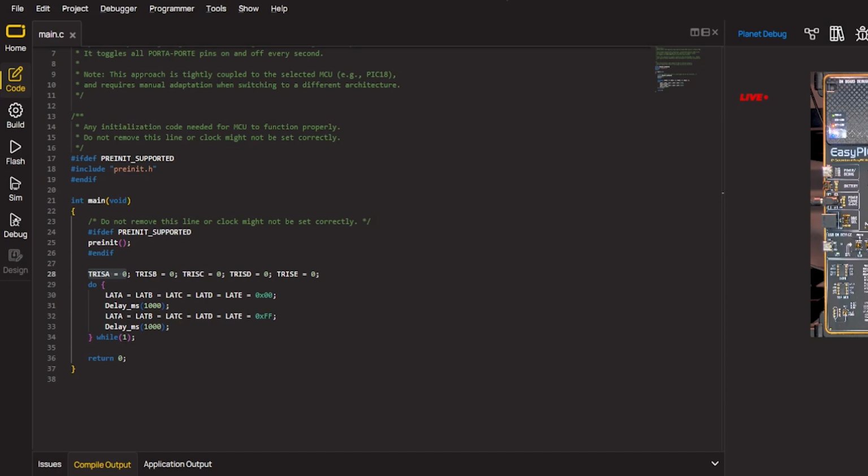And why are we doing this? Because we want to control the state of those pins, turn them high or low, which you can only do if they are outputs. So right now we have made the entire port bank act like output drivers. Okay. Right, next is the do while loop. This starts our infinite loop. In embedded systems, we often run the main logic inside a loop that never exits, unless there's a hardware reset or power cycle. Let's now look at the LED toggling logic.